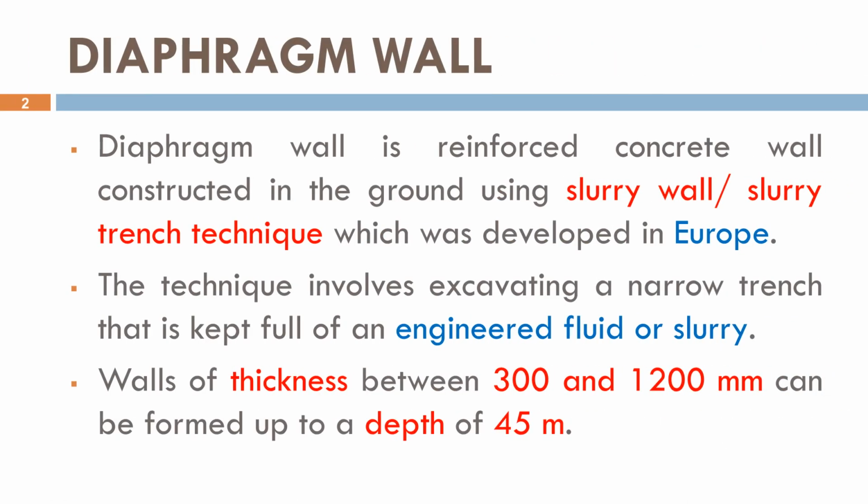A diaphragm wall is a reinforced concrete wall constructed below ground level using the slurry trench technique, which was originally developed in Europe. In this method, a narrow and deep trench is excavated while being continuously filled with a specially prepared bentonite slurry. The slurry prevents trench walls from collapsing by exerting hydrostatic pressure against the surrounding soil.